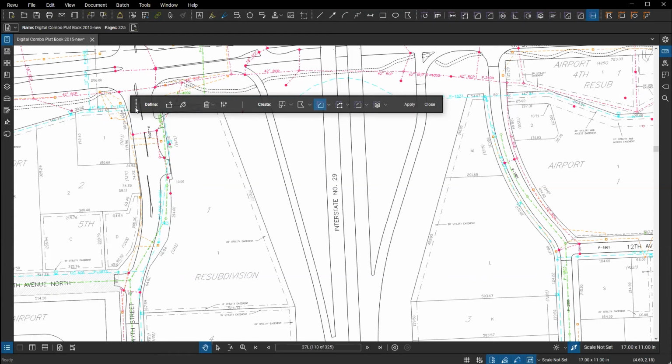If you want to just outline that with a polyline, or you've got certain shading that means certain things inside of the process. You want to highlight to be green means this, and orange means something else. You can put those phases inside of there, what have you. Or it could be for certain measurement tools that you want to leverage with an area measurement or a polylength, perimeter, volume. You can choose one of those functions here.